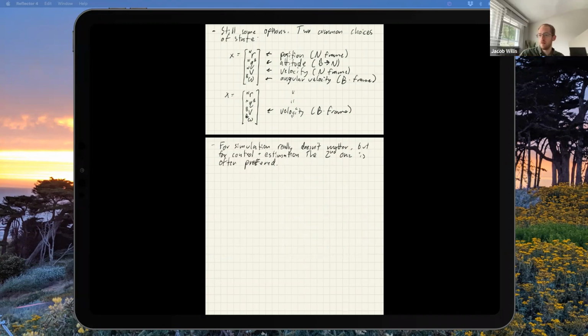A justification for using body frame vectors that I've seen is that aerodynamics are in the body frame, and your IMU or accelerometer measurements are in the body frame, and so if you're integrating those... Yeah, so those things are all unequivocally true. Practically speaking, you're going to end up rotating stuff back and forth either way, and we'll do this in a minute. Gravity's always in the inertial frame, right? So you always have a mix-and-match situation where some things are inertial and some things are body, and you're rotating stuff.